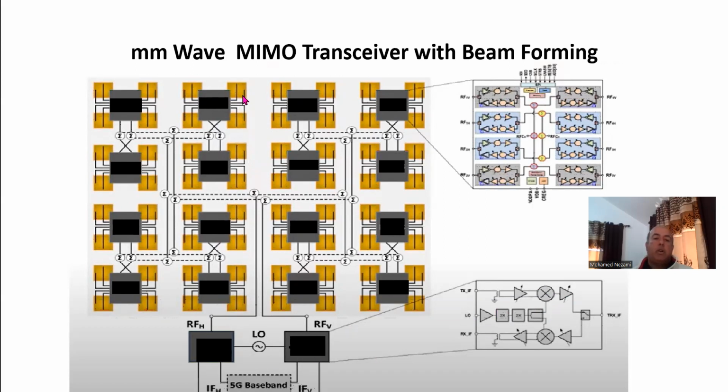So you can see that the antennas are dual polarized. There's 2 distribution networks. There's 2 passive, 16-way passive networks. You got split 2 ways here, 2 ways here, 2 ways here, 2 ways, 2 ways. So you got a 16-way splitter divider in the transmit path, and in the receive path it's a summer, of course. This is becoming a standard implementation, so I'm going to just follow that, except a little modification: I added filters as well, because this circuit does not really show the filters, okay?